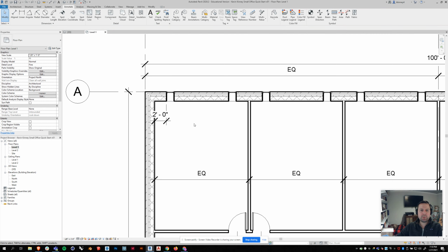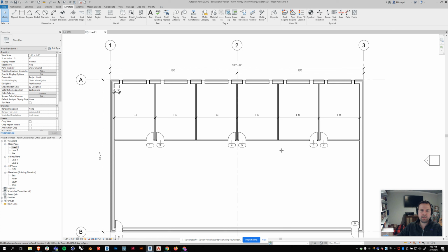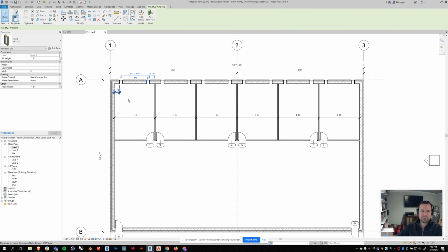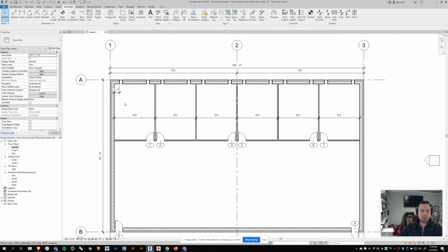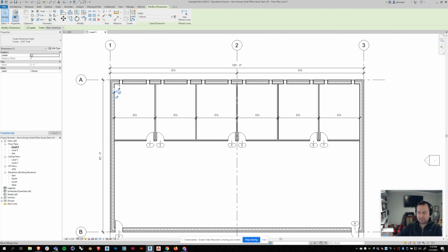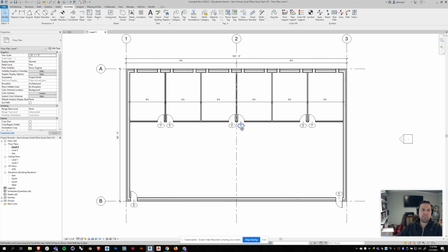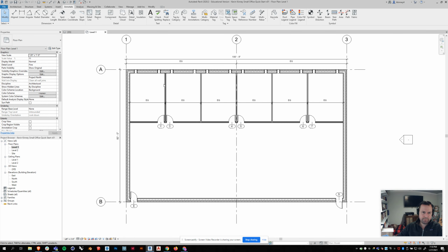Now, the only difference between this and temporary dimensions is that if I printed this floor plan, this dimension would show, right? It's on there. Well, when I click this one, the temporary dimensions appear. So here it is, 2 foot. Now I've done the adjusting I need, so I'm just going to get rid of it. So that's another way to get those temporary dimensions back if they disappear or glitch out: you can bring it back by just making your own dimension.